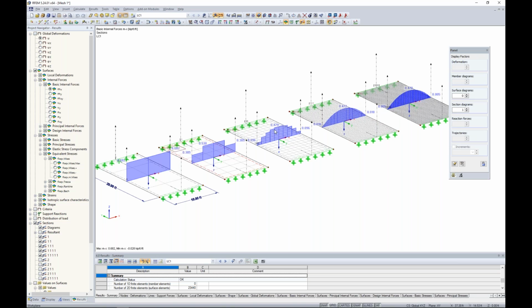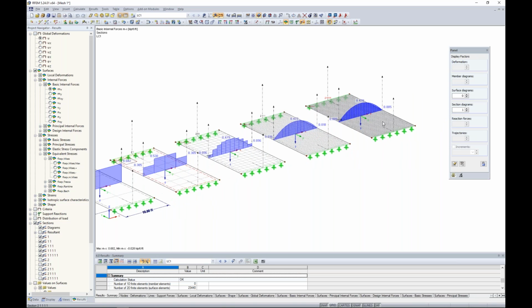But again, take a look at the max bending forces, 0.479 kip feet, 0.472, 0.47. So very little difference when we're looking at some of these surfaces towards the end here with an increase in FE mesh. So I would argue that maybe the second to the last, or possibly even the third to the last, just depending on your structure, is adequate for gaining those accurate results while not waiting forever for your solution to run.